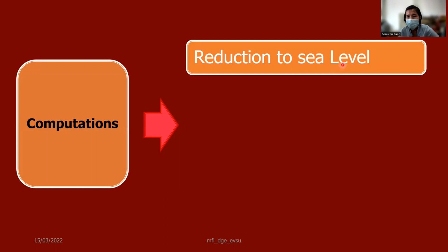That's why we need to reduce our baseline measurement, since the earth is curved and has curvature. And during the observation, we measure only the horizontal distance, or a plane. So we need to correct that, and reduce it to sea level, or our level surface of observation.